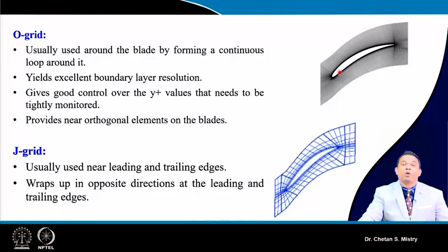Just understand what is happening on my suction surface and on my pressure surface. That is of our interest, because it represents the work-done capacity of the individual aerofoil. If I consider a blade, it comprises a number of such aerofoils, so for each aerofoil we need to have these details available.